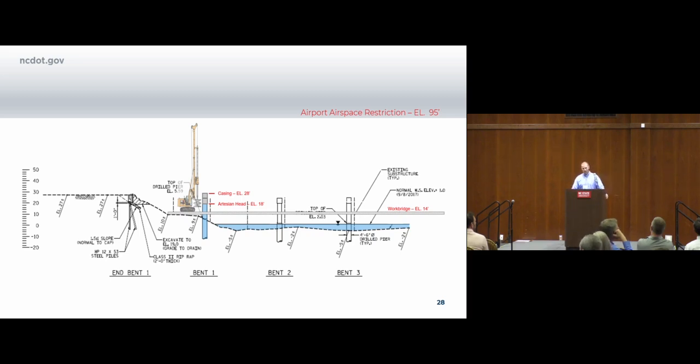I think at that point we ended up putting flowable fill into the casing to try to just stabilize the sidewalls because we didn't want it blowing in. So they filled it up with flowable fill to a certain elevation, and then we ended up welding. Actually, we may have welded on casing first. We were originally just above the work bridge, and they ended up welding casing on another stick of casing, and it continued to come up over that.